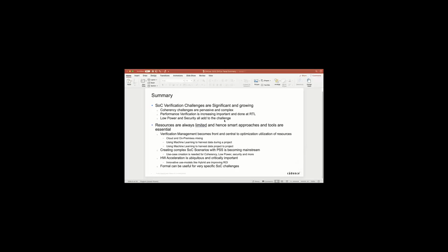No, there's no magic bullet. Obviously you can do chiplet verification with, for example, let's say you're connecting two chiplets with CXL or CCIX. You can use VIP to a certain extent, but ultimately there is cache-to-cache across the two chips. That is not just interface protocol, it's system-level protocol.